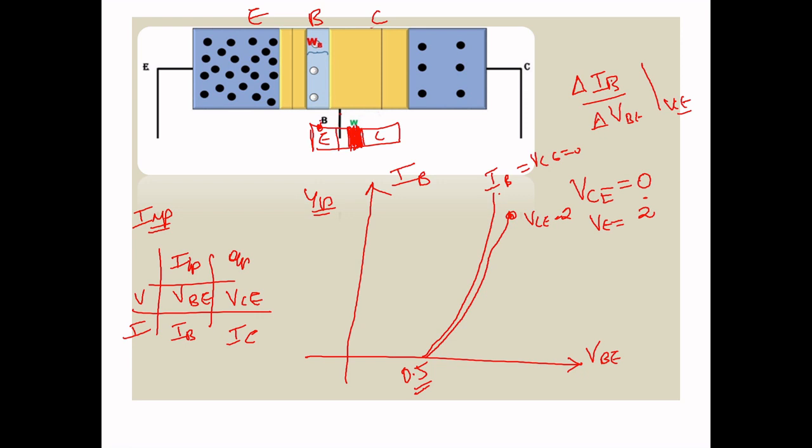So initially consider that 10 electrons combine in the base to produce a current. When you consider the second case, because of the lower area of the base, very few electrons are able to combine in the base and produce current. Consider 6 holes are combined and the corresponding current is plotted. So the remaining electrons will move to the collector part. The collector current we are not discussing here; here we are discussing the input part. So that is the reason why the current is reducing.